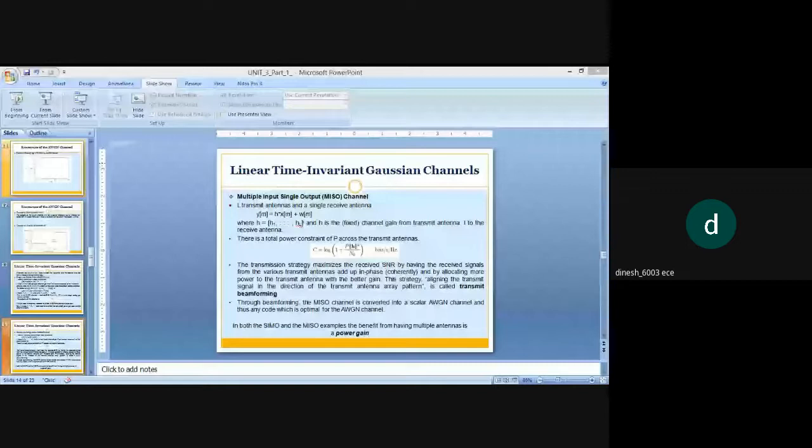So coding across subcarriers, across this information bit subcarrier 1, 2, can still be useful in practice, particularly when the block length for each subcarrier is small, in which the coding efficiency effectively increases the overall block length. So this diagram represents the information bits which are being passed on to the encoder subcarrier 1, encoder subcarrier 2, then to the OFDM modulators if required, then to the channels which are used as users.